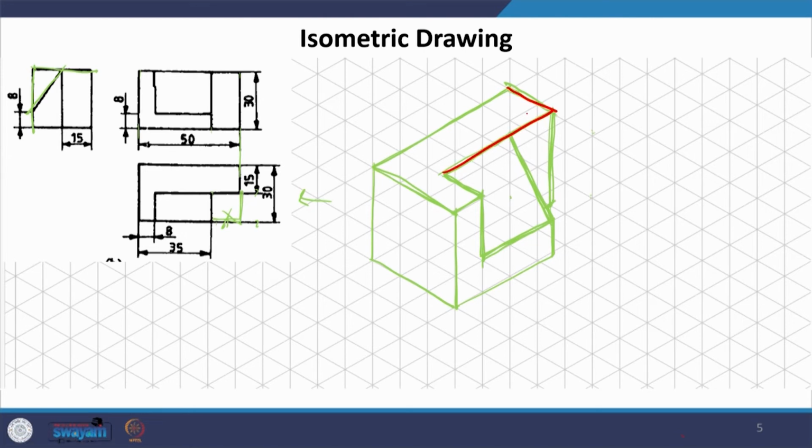And then we will match the orthographic projections which were given to us in the initial phase. So, this is what it is. Look at it in the plan. We have one continuous surface which is coming here. We have another surface. What this surface is, is actually an inclined surface. When seen from the top, it is appearing as one surface like this. This is what it is.